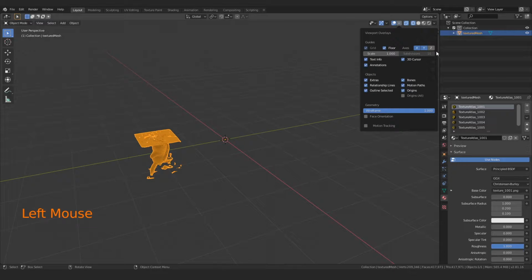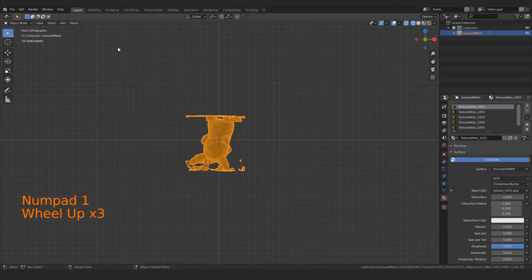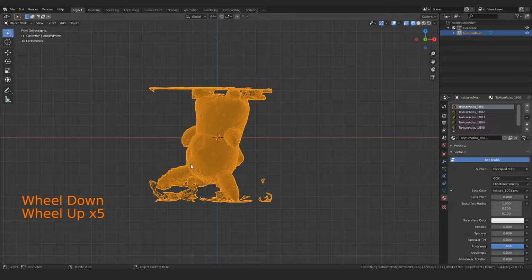And like I said before, the Z is hidden unless we're in an orthographic view, which I can show you really quickly. Currently, we're in a perspective view. If I press 1 on the number pad, you can see I've switched to a front orthographic view. And what this is essentially is I'm looking at the 3D world from what it considers the front perspective. And you can see that that's with Y coming straight at us. In other cases, this may be Z coming straight at us and Y going up. And essentially what happens is this flattens out the view into a 2-dimensional view.